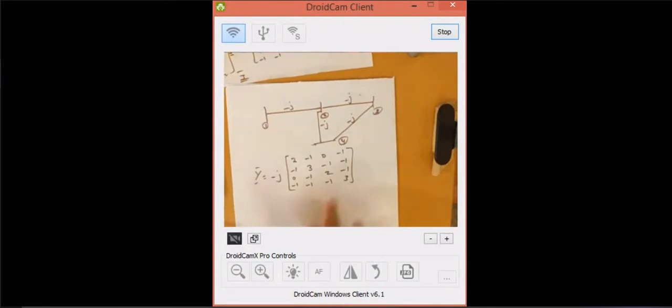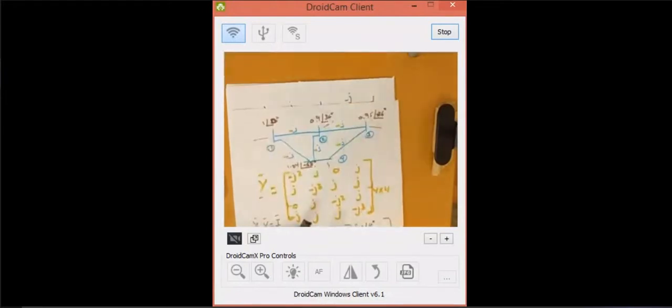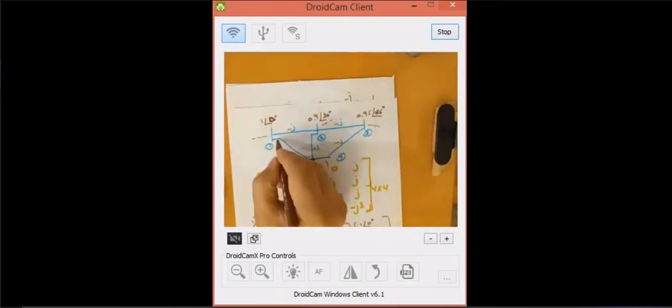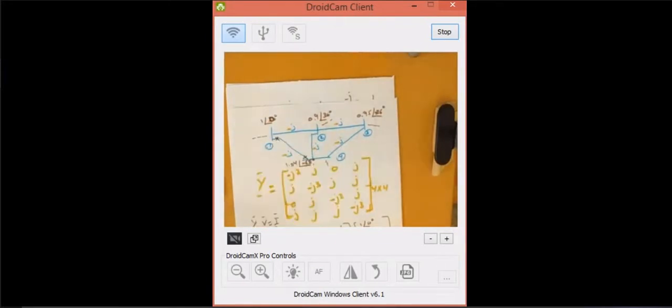But now there is some modification. So let me say that the line which is connected between 1 and 4, we want to disconnect it for maintenance. How to disconnect the line? It means that we have a circuit breaker here and we have a circuit breaker here. We open the circuit breaker on both sides. Okay, so it means that we disconnect the line. So how to find Y modified now?